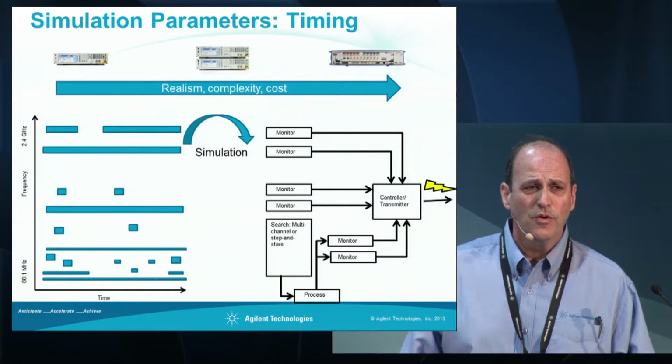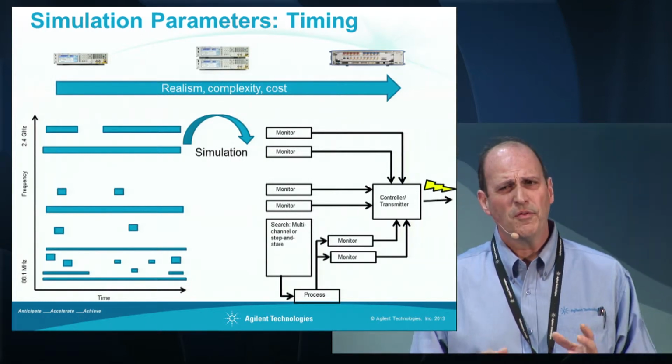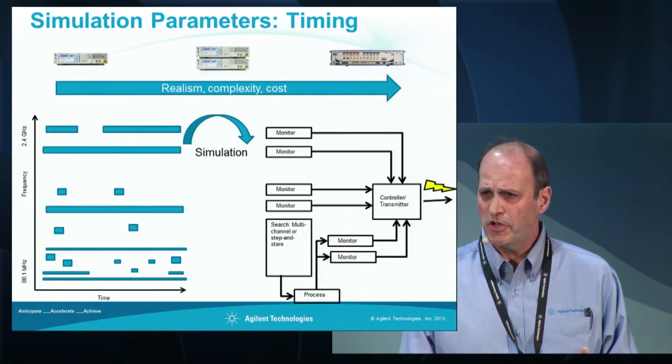So as we create these signals, really one of the basic questions the EW engineer needs to ask himself is, what is it you're trying to test? What are the goals of the testing? So if you're primarily concerned with specific frequencies, you might just have a list of those frequencies in the signal generator and test one at a time, test individually to see how it behaves.